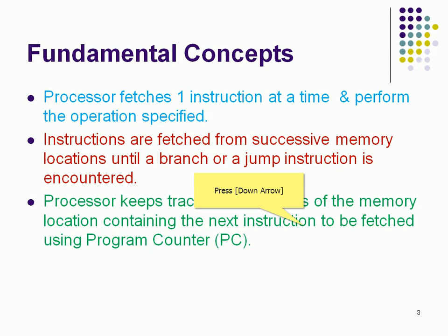The program counter is a register situated in the CPU premises, which always holds the address of the current instruction. Once the current instruction is handed over to the processor, it points to the next instruction in the sequence, and it is advanced by the word length of the computer. For a 16-bit machine, 2 bytes will be advanced. Similarly, for 32-bit instructions, the program counter will be incremented by 4. It depends upon the architecture how the program counter value is advanced.